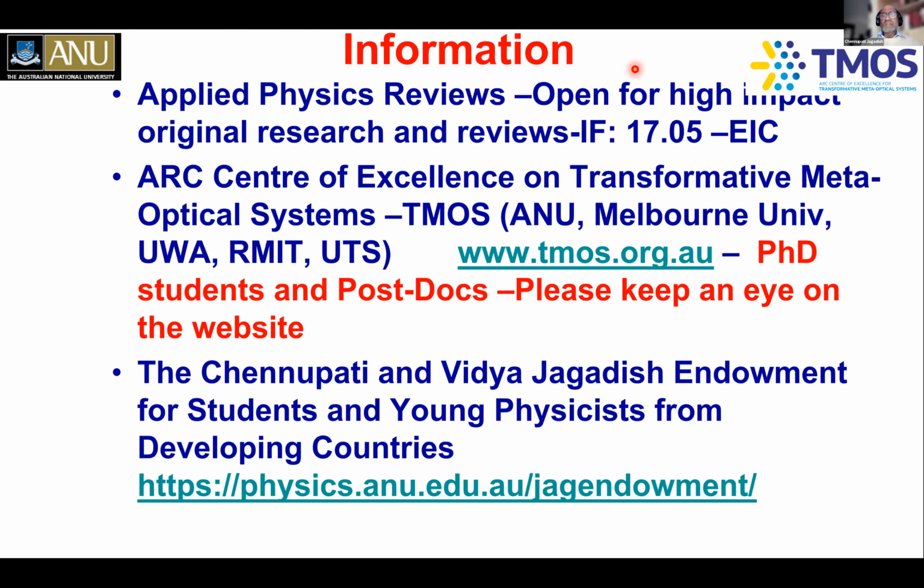Okay, so the ones which I've shown you till now, most of the nanowire solar cells are made out of this axial PN junction. So one part is acting like N-type and one part is acting like P-type. But actually that is not ideal, but that's the only one which people have reported, including us, for example. But what we're talking about is when you get these core-shell nanowires of the PN junction, the built-in electric field of the PN junction is the one which is really removing these carriers quickly outside this recombination region of the depletion region, for example.